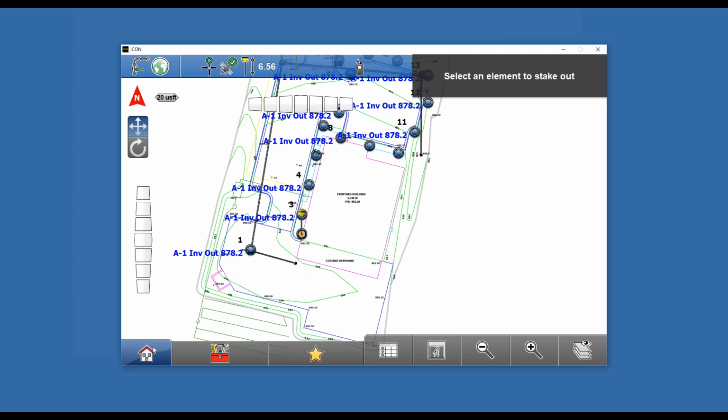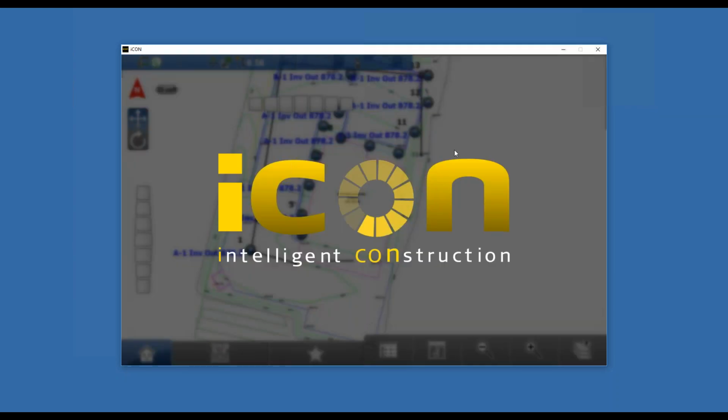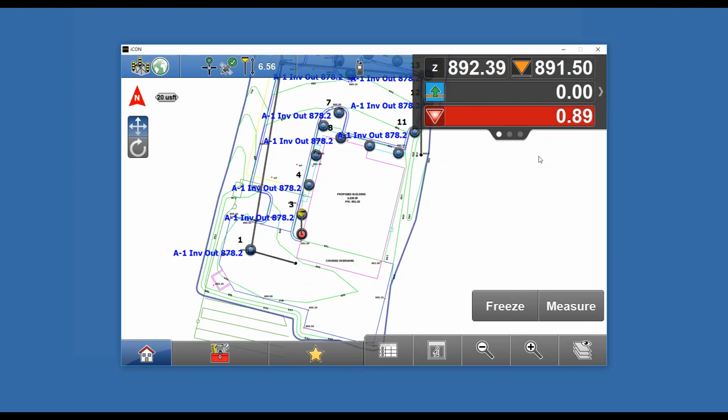So now just kind of show you a little more in the cut fill app, the other one everybody seems to use all the time. So now I'm using the surface model and walking around on site. So just like any other one working off a terrain model, anywhere I go on the job, it's giving me a cut and fill to my finish grade or whatever your model's made to subgrade. And up here, it's giving me my cut and fill, showing my current offset value.